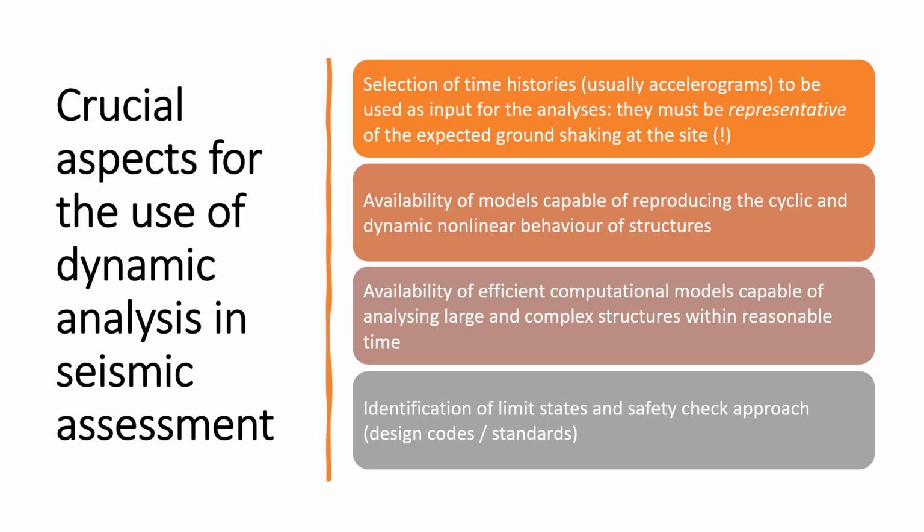There are several aspects which are not trivial that need to be considered with care, with attention, when you use dynamic analysis in seismic assessment. In particular, the selection of time histories, which is the input of dynamic analysis, normally accelerograms, is a key aspect. In the past, this was one of the obstacles for the application of time history analysis.